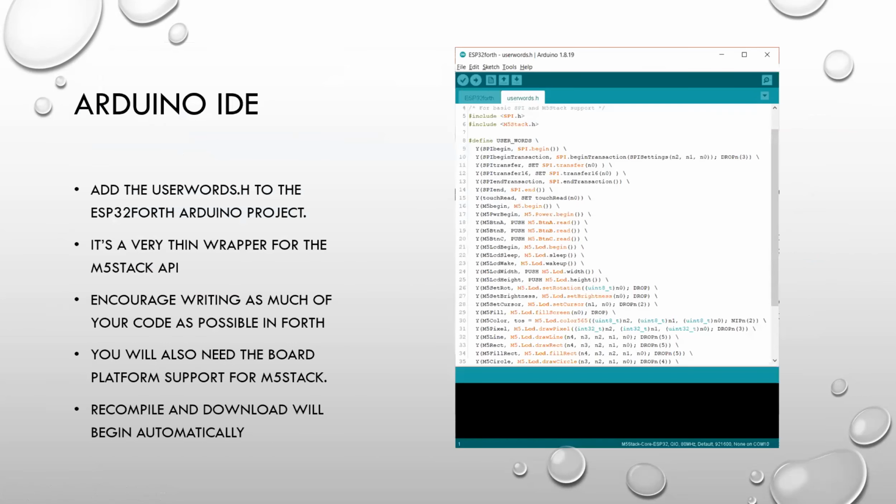Okay, so now what happens with the M5 Stack is that in addition to the ESP32, it actually has a helper ATmega328 underneath it. So in order to use all the other features, essentially the ATmega acts like an I/O expander, if you will. That's why it's necessary to start with M5 begin.